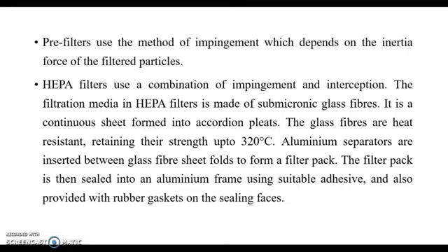This filter is made of submicronic glass fibers, and aluminum separators are inserted between the submicronic glass fibers. These fibers are heat resistant, retaining their strength up to 320 degrees Celsius. The filter pack is sealed into an aluminum frame using a suitable adhesive, and is also provided with rubber gaskets on the sealing faces.